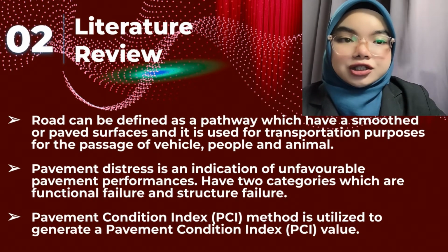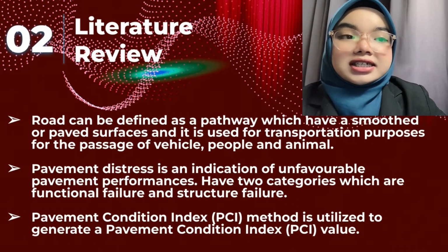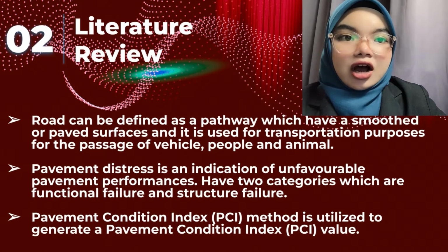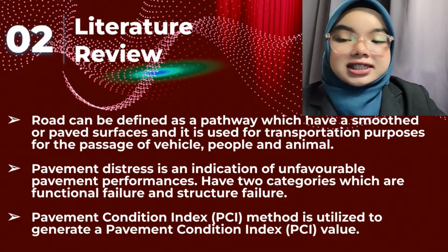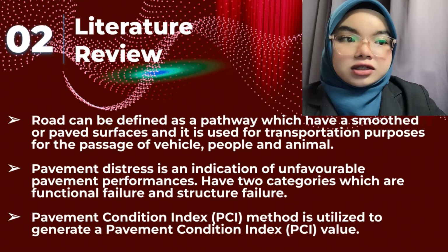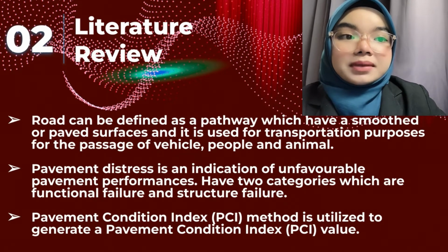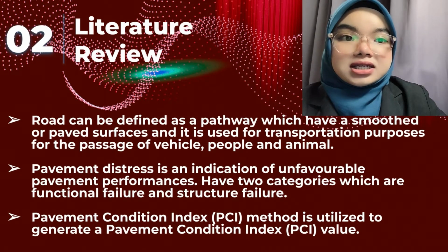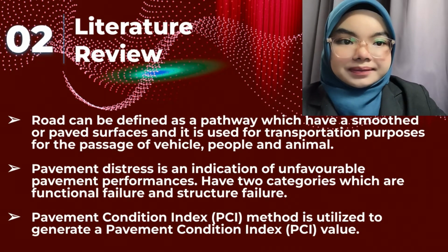Next is pavement distress. Basically, pavement distress is an indication of unfavorable pavement performance. It is classified into two different categories, functional failure and structural failure, which depend primarily on the degree of surface roughness and consolidation or shear, respectively.